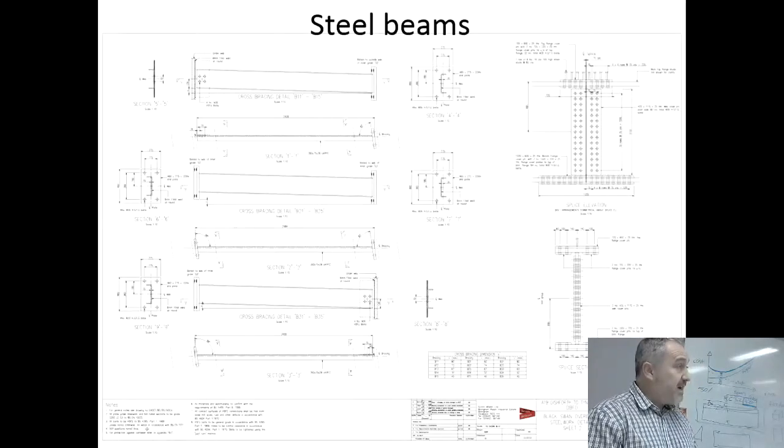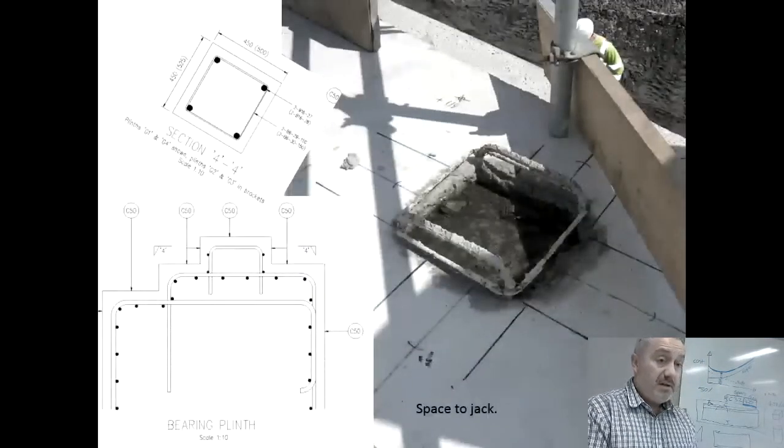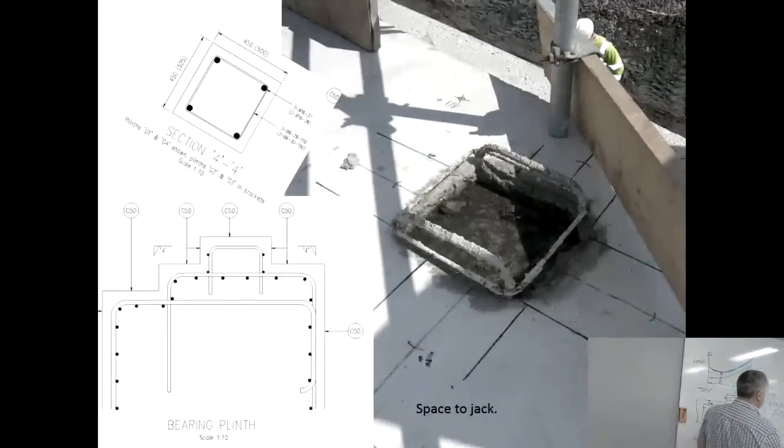Have you got a specified bearings at all? What I'm saying is that if you've got the bridge on top of the retaining wall, you have a bearing here so that if there's any sort of movement. But what happens is that these bearings tend to only last 25 years, so you have to put a jack in there somehow and lift up the bridge and replace these.